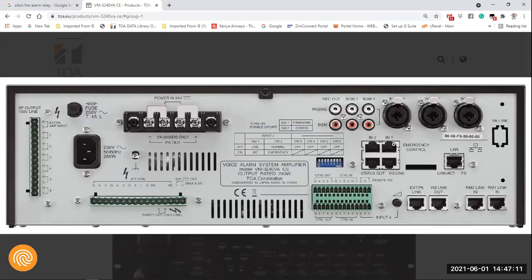If 2 or more detectors pick up smoke in the same area, that same fire panel will then switch on another different relay. In this case, this becomes relay number 2. This becomes your green, green, white to then evacuate. So single knock will be your orange, orange, white colors, and then your double knock will be your green, green, white colors. So you need 2 relays on site tomorrow for you to be able to have the system automatically trigger. All right. Okay, are you guys good?